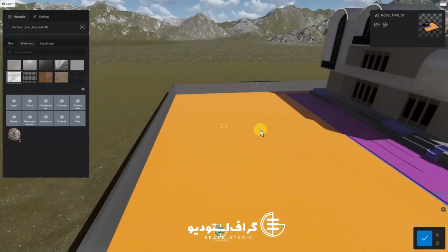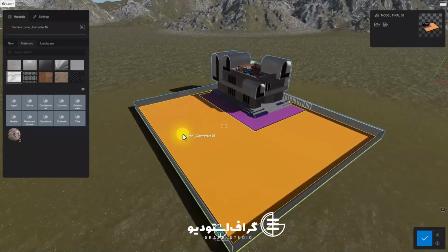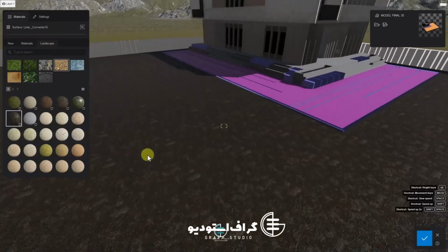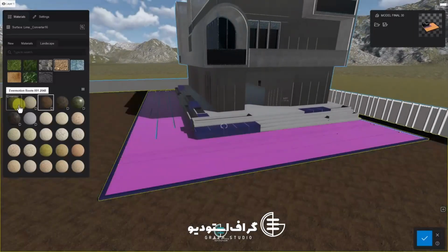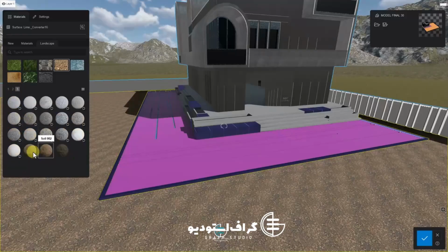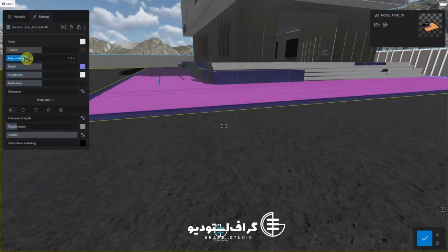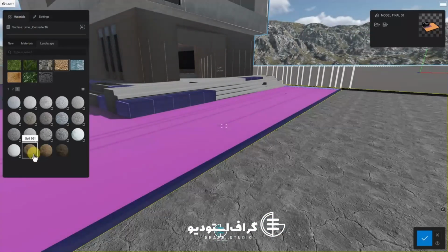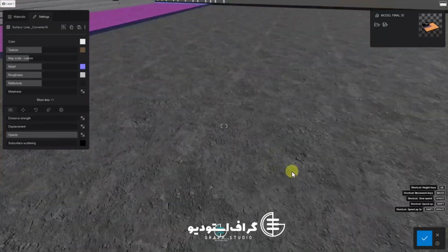Actually, use the one we created, because the first option, if I press delete, which we mentioned many times, only clears the slot, and the material remains in the scene. If you select the other option, it deletes both. Okay, that's what we wanted. This one too. Let me edit this one too. They got lost. I don't know which ones they are. I bring it and assign it to this one too. See? I assigned it, and it still shows black. So, what's the solution? A normal modifier, collapse all, and it becomes a single object again.